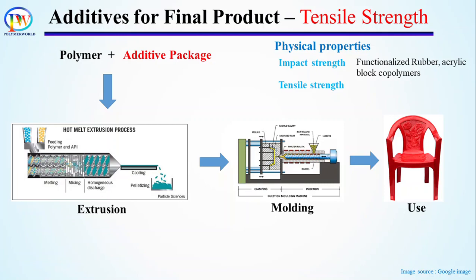Since the strength requirement of household stuff like chair will be less compared to polymeric composites used in car or aeroplane application, reinforcing agents are also different for these products. When high strength is required, glass fiber, carbon fiber, or Kevlar fibers are used as reinforcing fillers. In case of moderate strength, talc, clay, mica are used as reinforcing filler as well as cost saving filler.